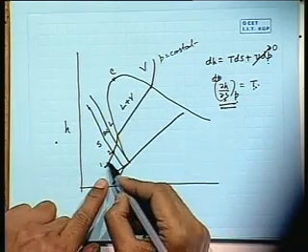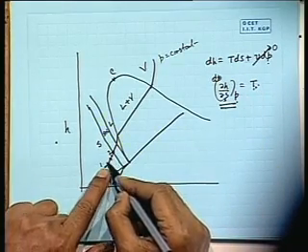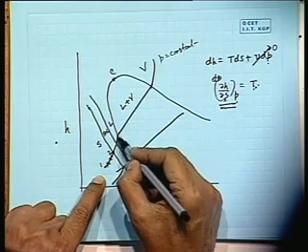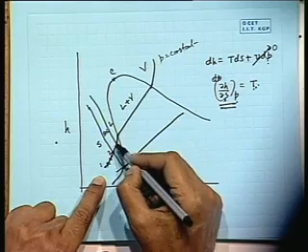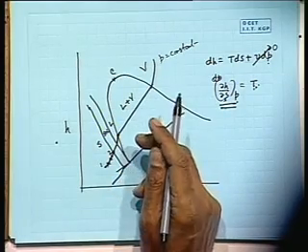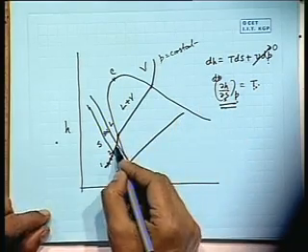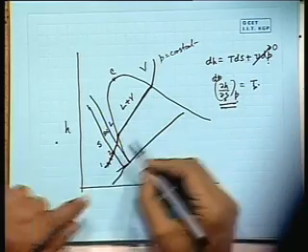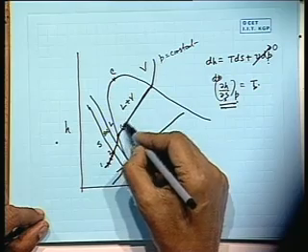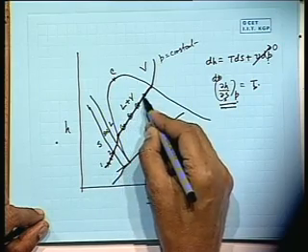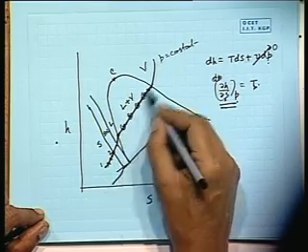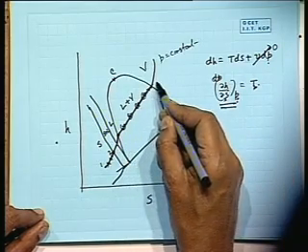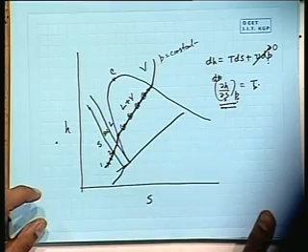Now when we go on heating, at each and every point on the sensible heating part, the temperature is changing, increasing. So this curve has an increasing slope, steep. If you draw this qualitatively like this, it will tell you that your concept is clear. Whereas when you draw this curve in this portion, it is constant. Why? Because T is constant. When the phase change is taking place, at each and every point T is constant during the phase change, solid to liquid or liquid to vapor. So (∂H/∂S) at constant P is constant. That means it is linearly increasing. As you go on heating, both the enthalpy and entropy are changing.